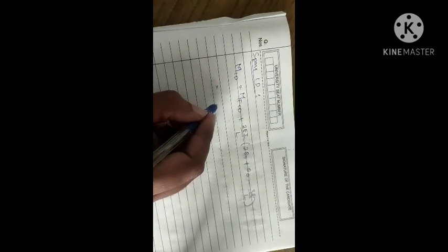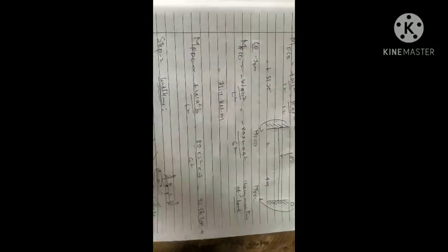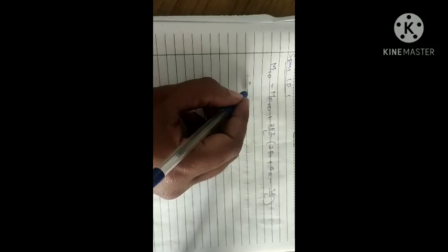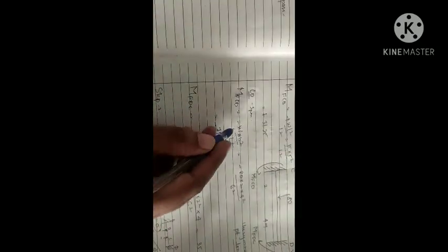Using the formula, we have calculated it for the symmetric case. So go for FEM itself. What is your FEM? FEM is 71.11 and MFDC is 35.56. Remember this, 71.11. So this is minus 71.11. We have not written the minus, but it should come here.